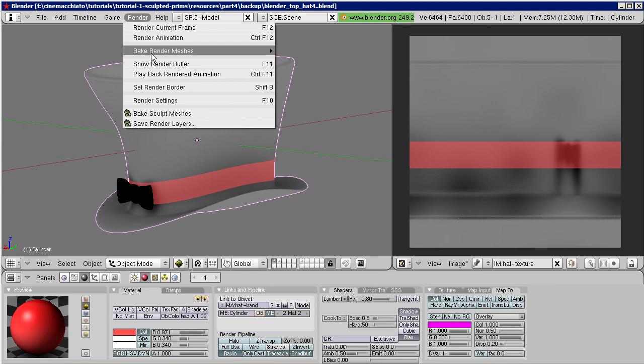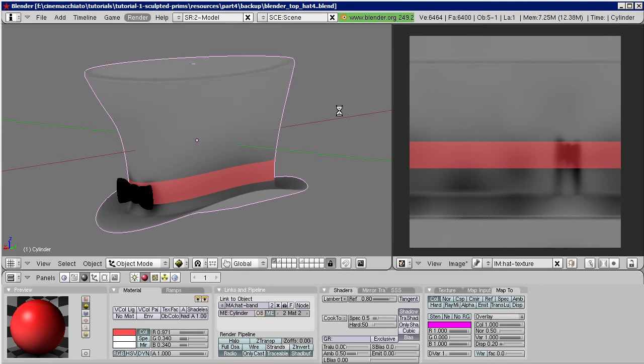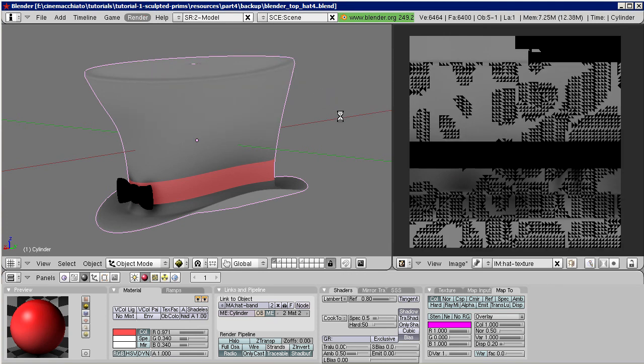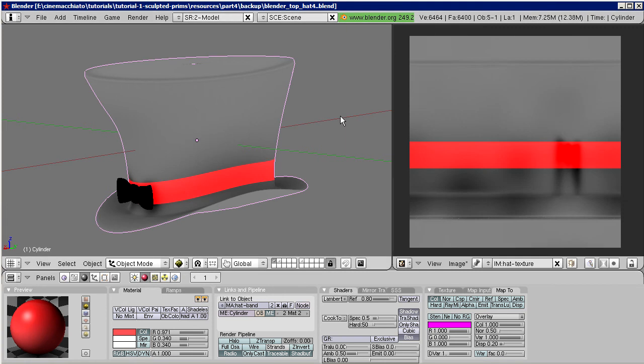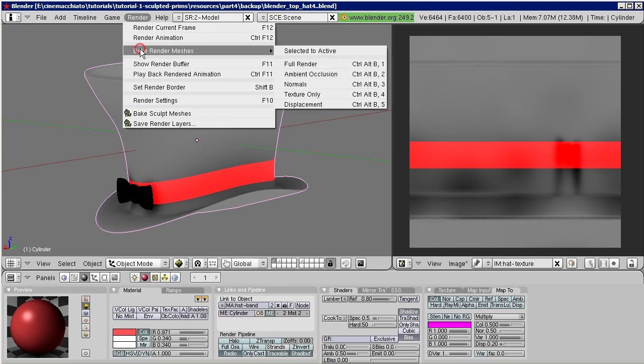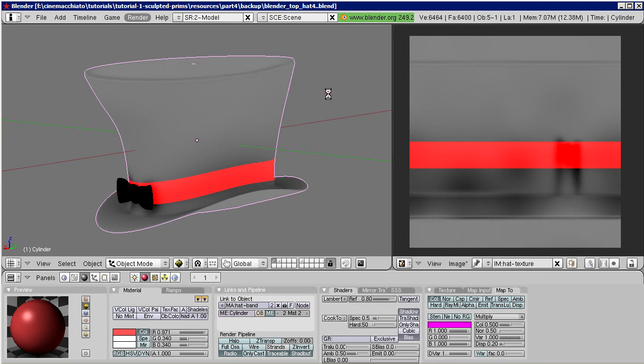This will result in a much crisper color definition, and still contain the ambient occlusion. Another, and probably the best option, would be to use the ambient occlusion map as multiplier on the hat band. So it does only affect the light intensity of the texture. You will need to play with the color value, until you get a convenient result.